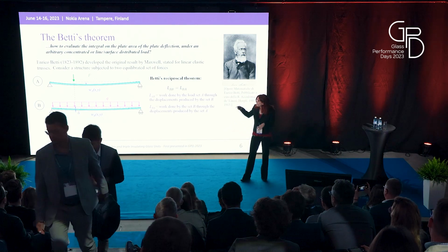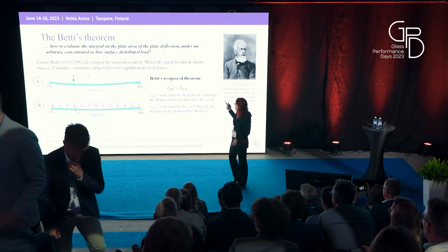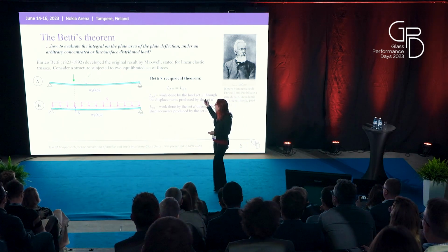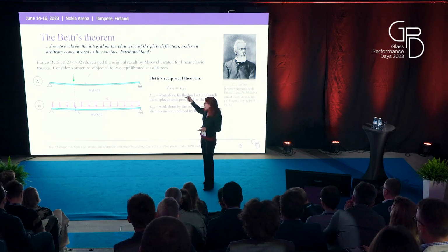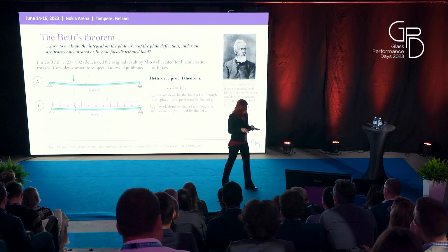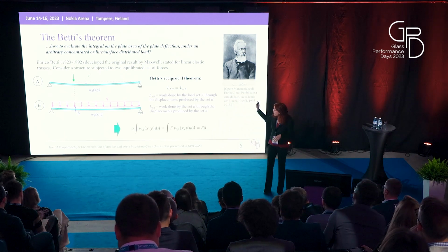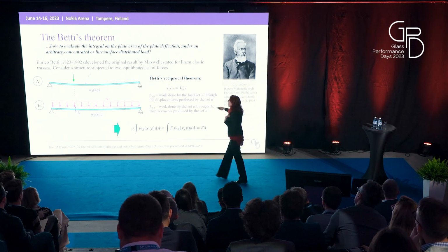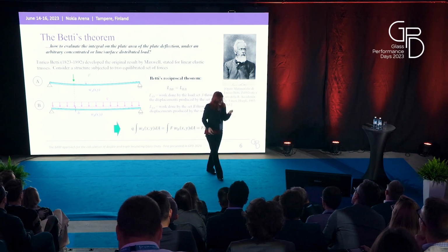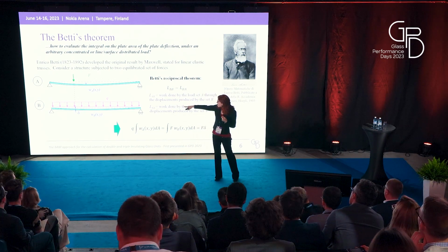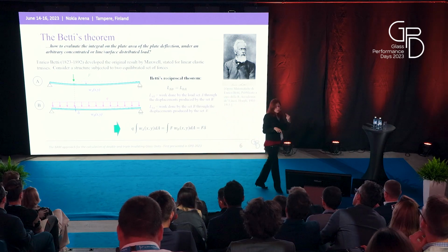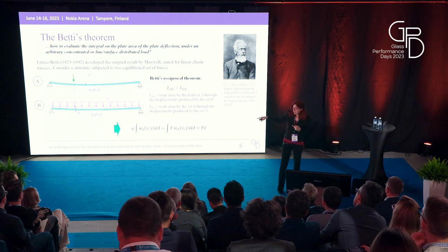So if we consider, for example, a simply supported plate, here it is represented as a beam, but it is a plate, subjected to a concentrated load as system A, and as a system B, the same plate under a uniformly distributed load, Betti's theorem allows us to evaluate the integral over the plate area of the displacement in system A just as a function of the quantity delta, so of the deflection of the plate under a uniformly distributed load, measured at that point where the load is applied.